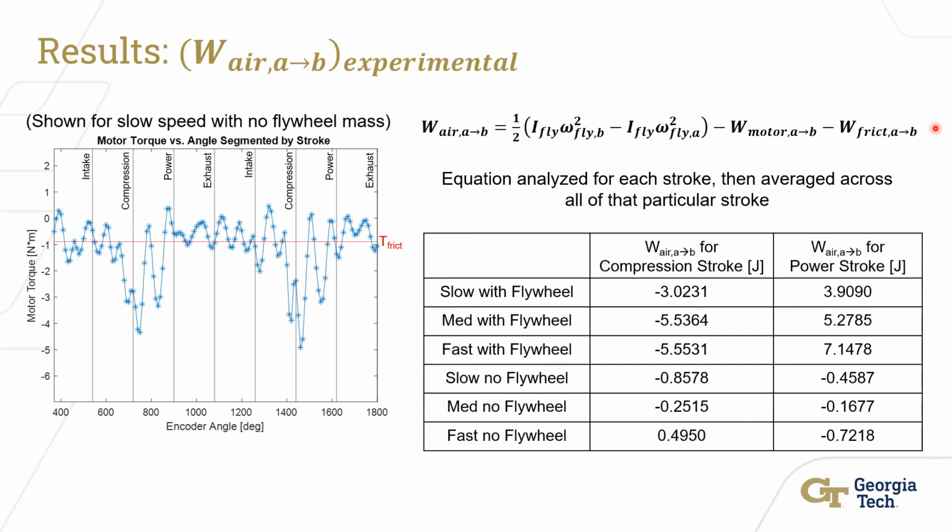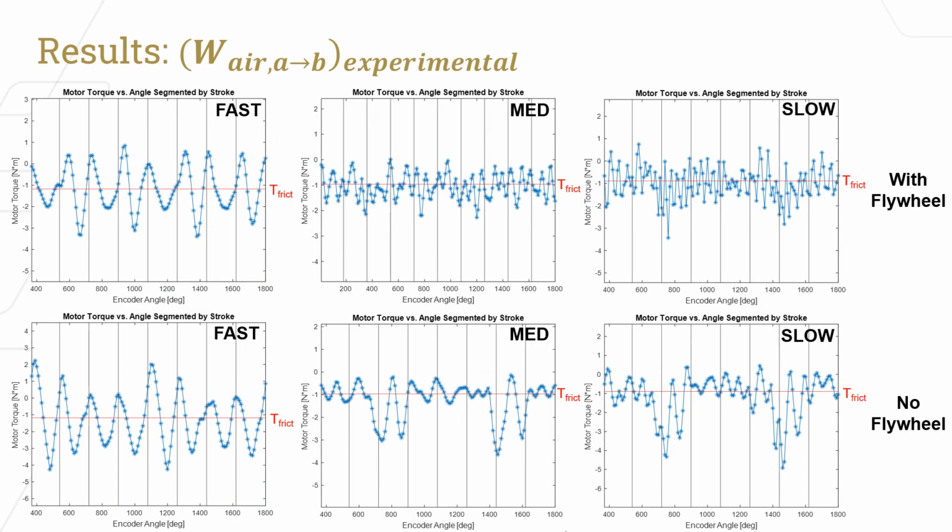First, there is noise in the data. Noise can explain the changes in work of air with engine speed. When holding the inertia constant, the magnitude of change in the work values isn't that large. A much larger magnitude of change can be seen between the work values of the two inertia settings. This is mainly due to the fact that with low inertia, work of the piston comes into play, which we assume to be zero. Therefore, with better signal processing such as using a fast Fourier transform and better modeling assumptions, the results in the table should more accurately meet our expectations.